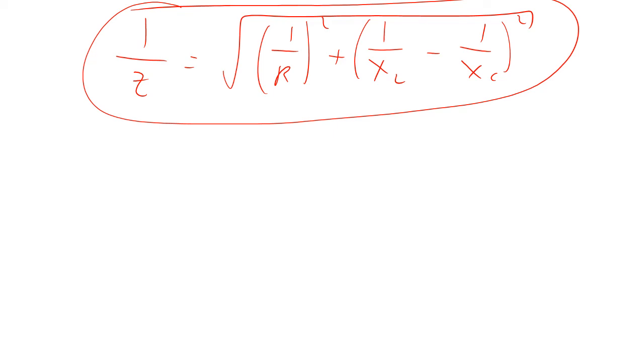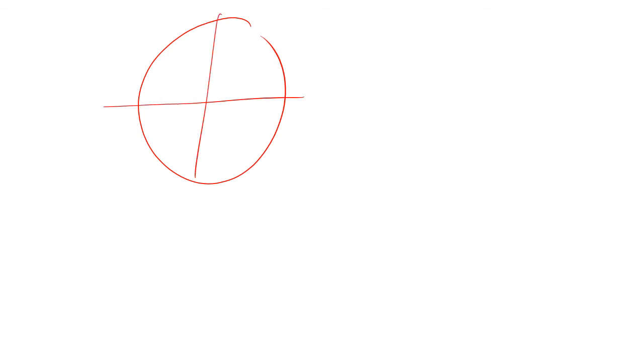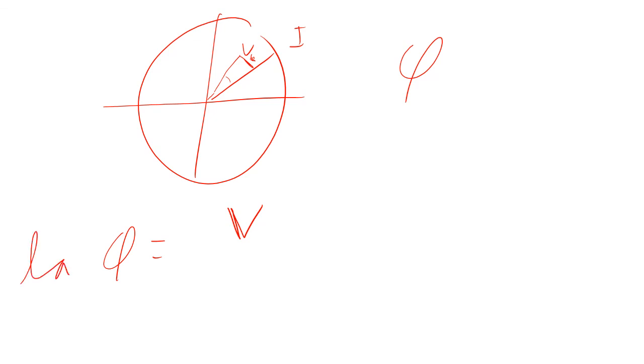Notice also that as we did this, for the series circuit, once again we had I here, but the total voltage was right there. So there's a difference in there. There's a phase angle. So the tangent of the phase angle is going to be VL minus VC divided by VR, which was that right there.